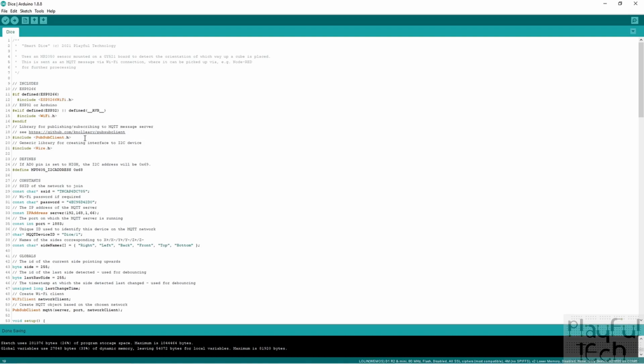There's many different ways we could send that message. We could send it as an HTTP request, we could have a web server that someone accesses, but MQTT is really great for sending lightweight, simple messages such as sensor readings, and it runs on a very small footprint. It doesn't take much memory or processor power or anything like that, so it's really good for sending messages between small devices like Arduinos and Wemos boards and things like that.